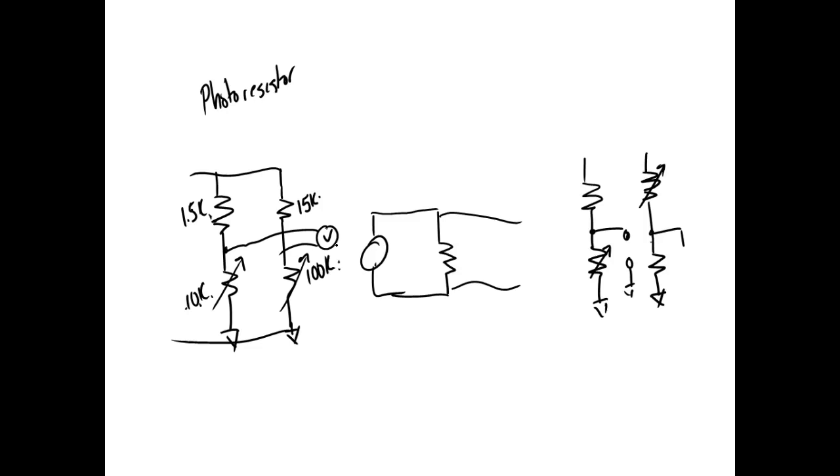Now on scales, we have a thing called a load cell. We'll talk about that later, but it's a Wheatstone bridge like this. But we don't use it to set 0. We set 0 in the scale. Does that make sense? So we'll go into the scale, and then we'll take all the weight off, and then we'll go in there and say that this output in the computer is 0.